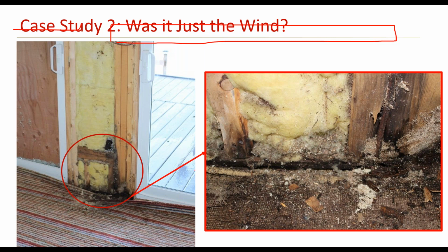Again, water was seeping in at this location, and it's a concealed space, and water and darkness provide plenty of food for microorganisms and biological forms of life. And you see wood decay that takes place over time. So it went undetected for years, and once the wind hit the wall, it found almost no resistance. As you can imagine, this now became almost like a piece of sponge held in place with a couple of nails. So it just moved inwards. And this structure was lucky enough that this severe wind just moved the wall a couple of inches and did not blow it out completely.